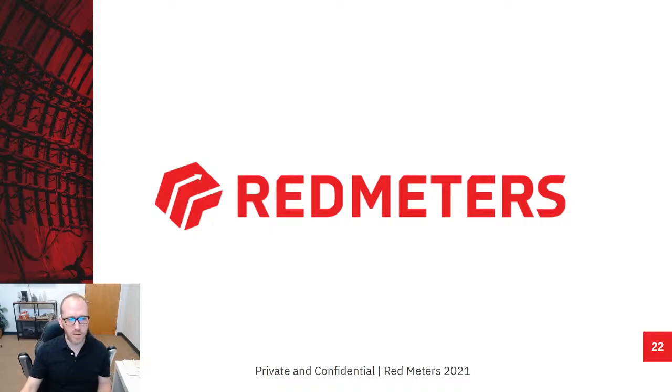Some people look at how powerful Cinder is, and they're going to say, well, can I just plug in other instruments beyond the red meter? Yes, you can. You can currently use Cinder to display pressure and flow because those values already come from discrete sensors within our ecosystem. As long as they have a 4 to 20 output, we have 4 to 20 inputs that they can connect to.